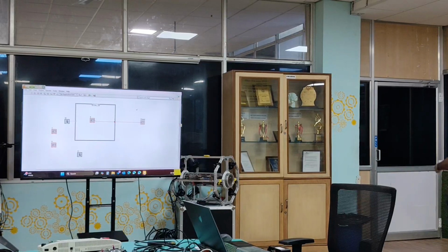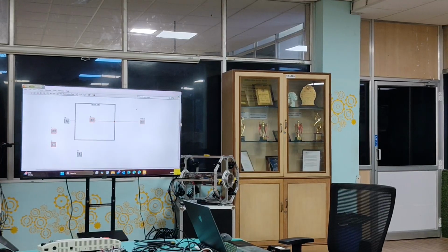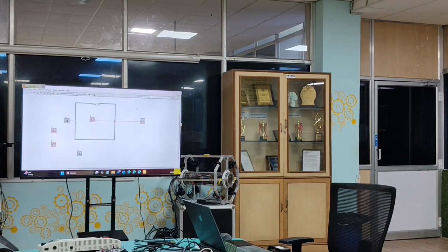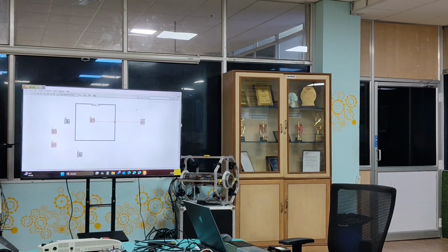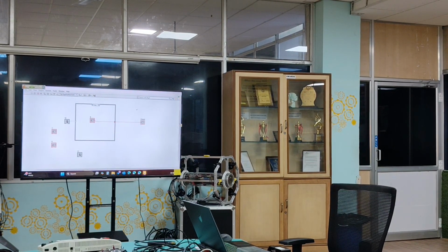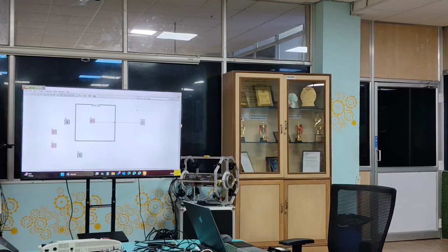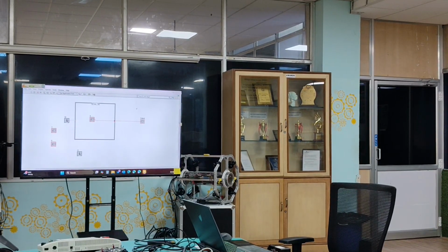Okay, you connected the first one, right? Go to the false case. Place the second variable inside it. Connect the same thing to the output variable. Go to the false case. Nothing is connected, so this one has a white color shadow. If you look into my screen, that has a complete orange color. It means that something is missing. So place one variable here, connected to the output terminal, it will work.